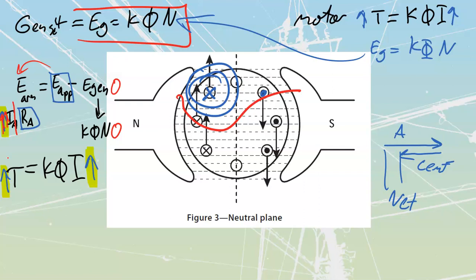Overloads are supposed to respond when we hit that point called the locked rotor condition. A locked rotor condition is where the rotating part, the armature of our motor, has been tied down by mechanical load. Usually, it's something that develops slowly over time. You're going to have a heavy load on the system, then your customer usually pushes the boundary with exactly how much they can take out of it, and then they don't do proper maintenance. And so you start having mechanical friction that really starts to build up. Every single roller along a big roller chain hasn't been lubed in a couple of years, and so you get all this extra friction and drag on there, and eventually this thing just causes us to stall out.